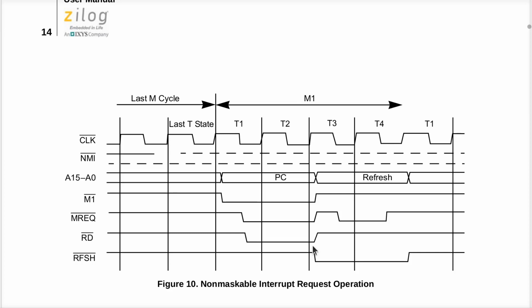So how is this supposed to work? Well, there's one and only one thing that the Z80 can do in response to a non-maskable interrupt, and that is to directly call a subroutine at a specific well-known address in the memory. And this M1 cycle is the fetching of the opcode of the first instruction of that, what we call an interrupt handler.